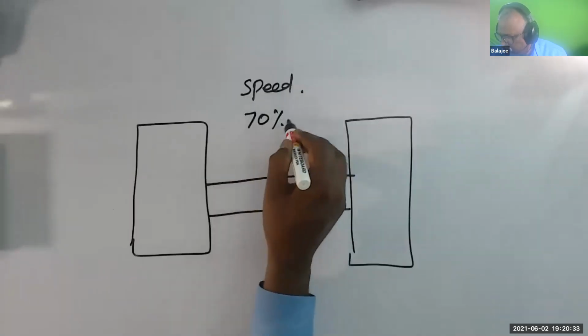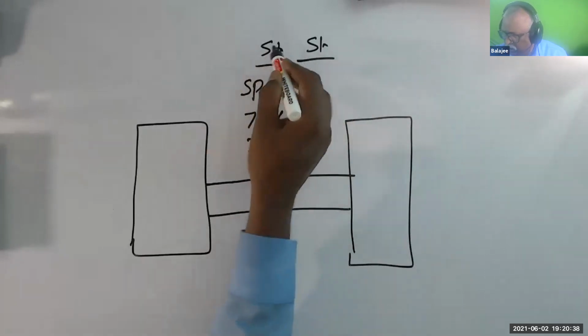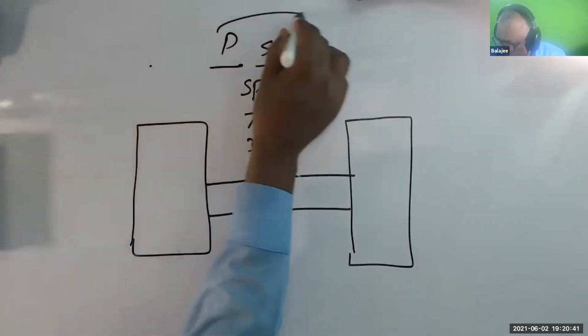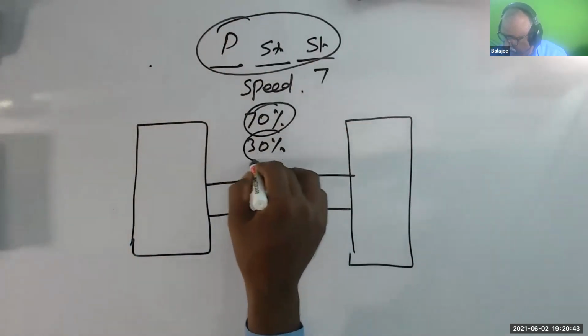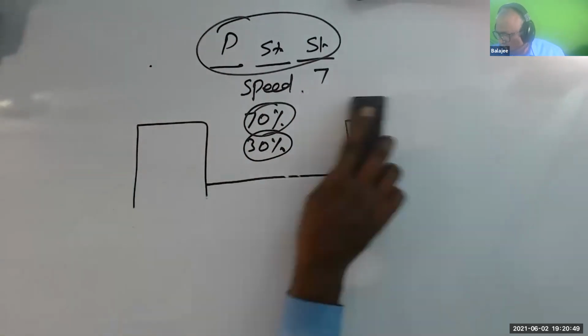Only 70% efficiency, 30% loss, because you send one start bit, one stop bit, and one parity bit. To send 7 bits, you are transmitting 10 bits. Because of that, there is a loss. So we have two issues. No, they are different. I'll discuss throughput and the rest later.